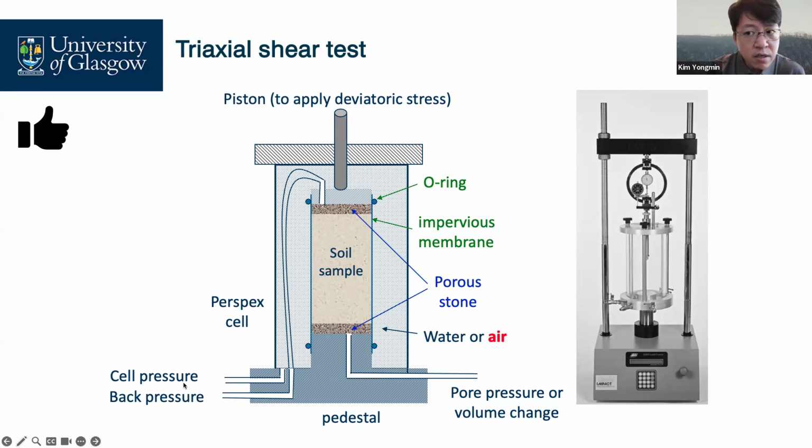We have another channel, the back pressure channel. It is connected to the top of the soil sample. We apply back pressure. Why? Last week, I explained to you. This back pressure is related to saturation stages.